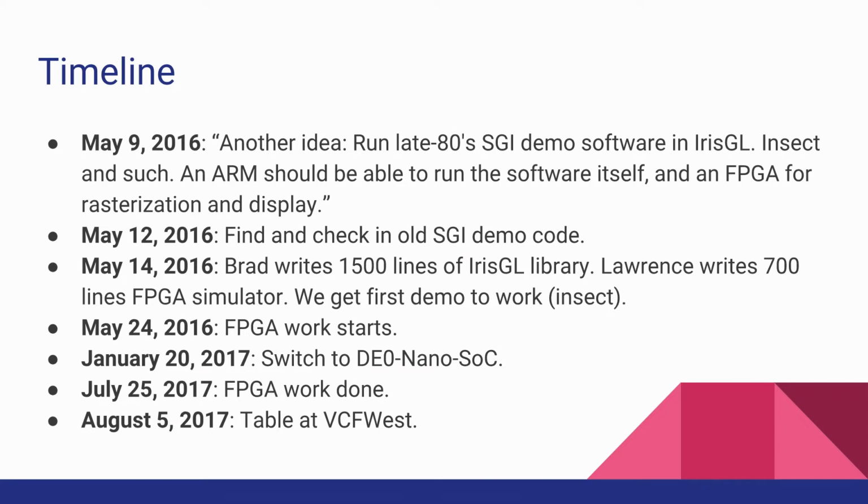But it was overwhelming, because the FPGAs, for example, are really good partly because they have 1 million pins, and they're all on the very bottom of the chip. So they use this chip kind of called a BGA, a ball grid array, which is really hard to solder. Then high-speed memory is really hard to deal with, because the signals have to be all the same length so they all arrive at the same time. It's way past what we could do. And so we kind of get stuck and bogged down.